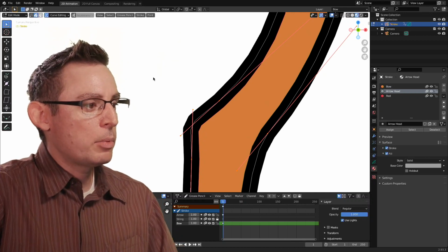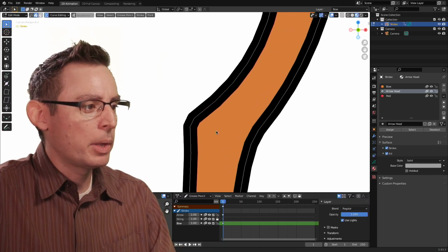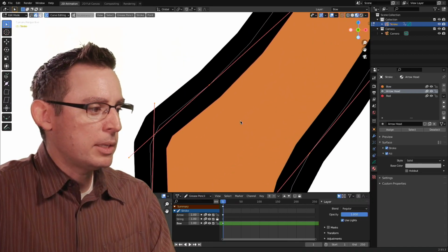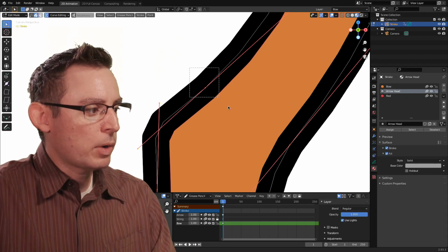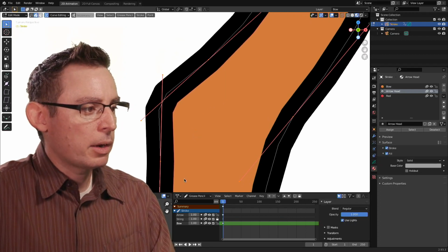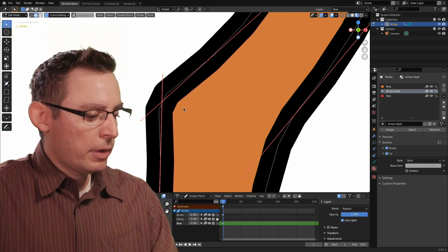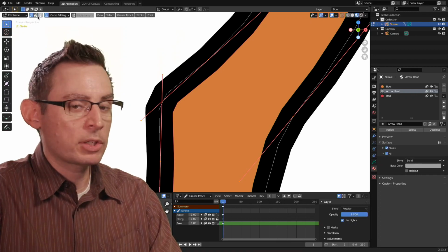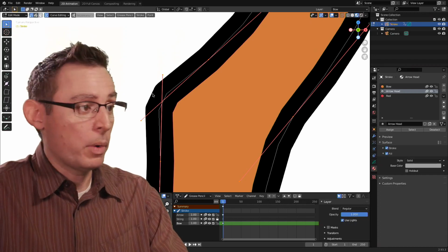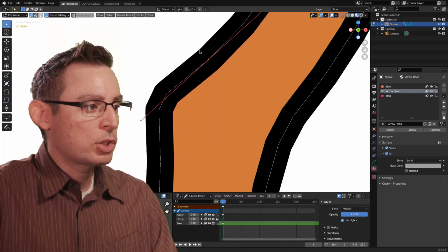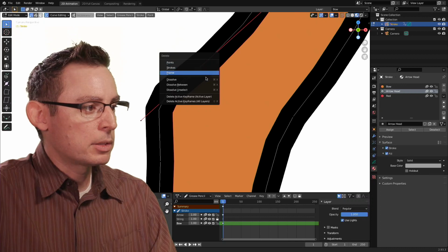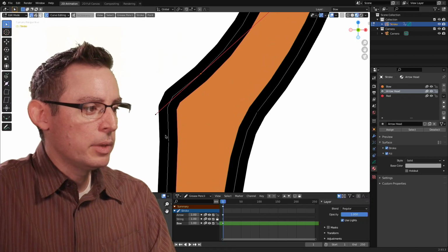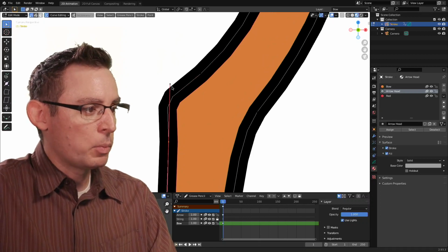Let's go back in. I hit the U key to enable curve editing mode. And now I can go in and start making adjustments to this curve itself. I can see right off the bat, and I'm going to zoom in, make these points real big. I can see right here there's a control point. And right down there is a control point. Well, I just want to have one. If I go into my point selection system, which is this first icon in our row of selection states, keyboard shortcut 1, by the way. Now I can go in and select just that one control point. I want to dissolve it to get rid of it. And now my guy kind of goes a little wonky. So I hit undo, because I think maybe the first step is to move this bottom one into that corner.